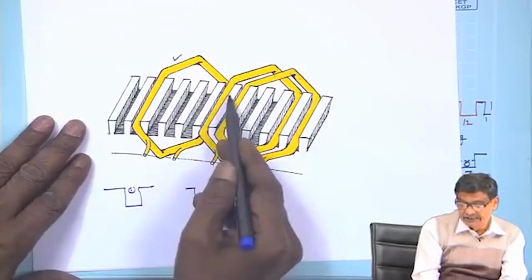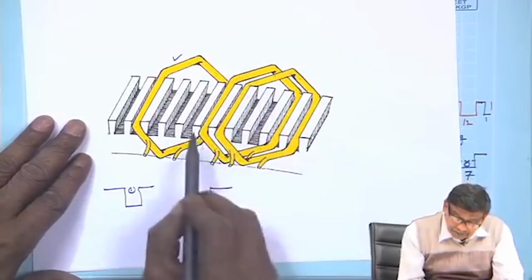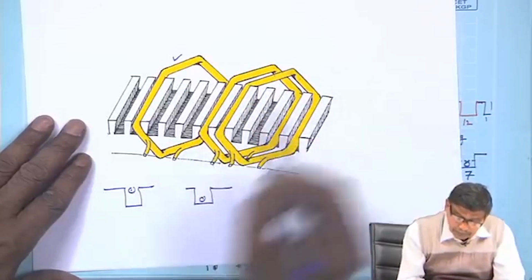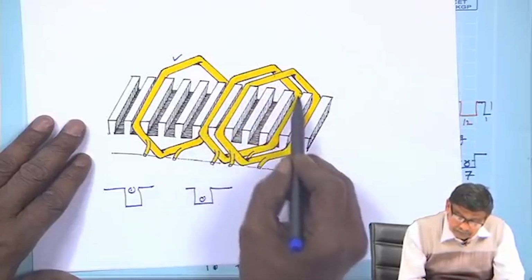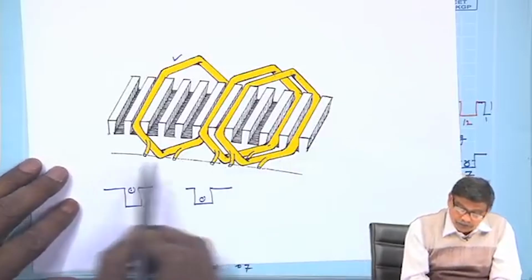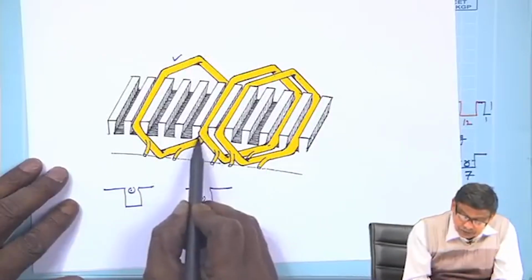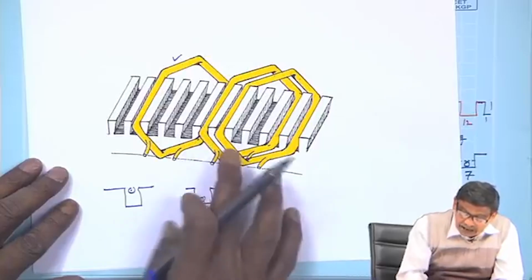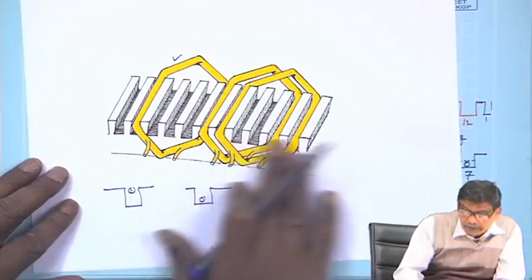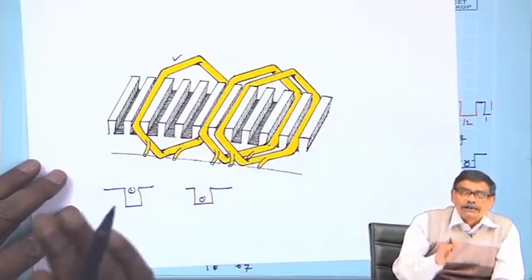You can physically see its return here, below this. Similarly, this is another separate coil, and its return is from below. So, in each slot there are 2 coil sides as shown here, and when the other slots are filled up, everything will have 2 coil sides, lower deck and upper deck.